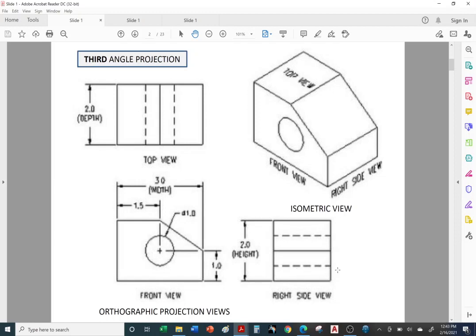If you ever have a solid line overlapping a hidden line on one of your views, the solid line wins because we can actually see it, and we actually draw the object lines thicker than the hidden lines. We'll talk more about the alphabet of lines, the line types, and the line thicknesses. All right, so let's go on to the next slide.